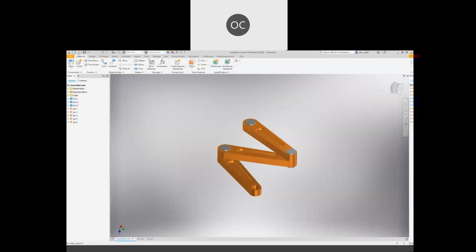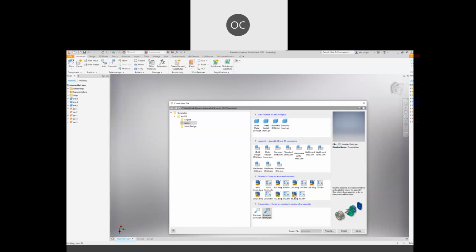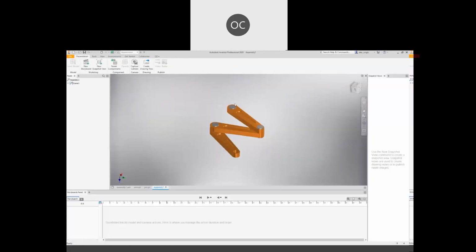So I would like you to go to the IPN environment again, presentation environment, IPN here. Okay, create. So bring in the assembly 1. Bring in the assembly 1 in your storyline here. You will see that view, right? That just now I stopped the view there. So please create a video using this assembly file.